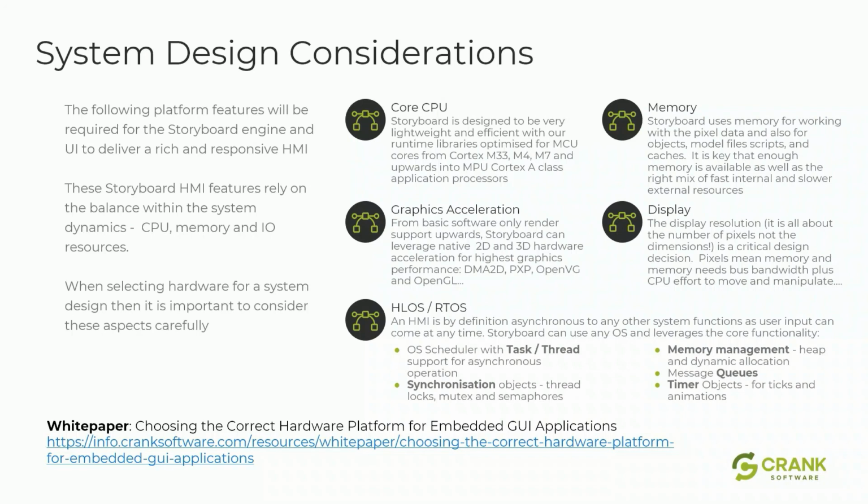And one of the big drivers really is the size of the display. So when you're choosing a display, it's not about the physical size, like 7-inch or 10.4 inch, etc. It's the number of pixels. So pixels means memory, and memory needs bus bandwidth to move and CPU to manipulate. We'll come on to that in a bit more detail.